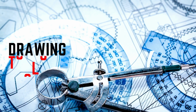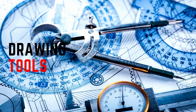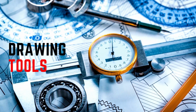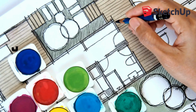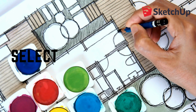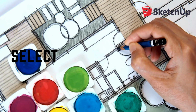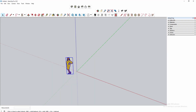Drawing tools. All of SketchUp's drawing and editing tools are available from the main menu, and/or the main toolbar across the top of the screen. Most of these can be activated by a shortcut key. Select. You need to select objects before the objects can be moved, copied, and scaled. You can also use Select to erase objects. Select then press the Delete key. When you activate Select and click on an object, it will be highlighted.